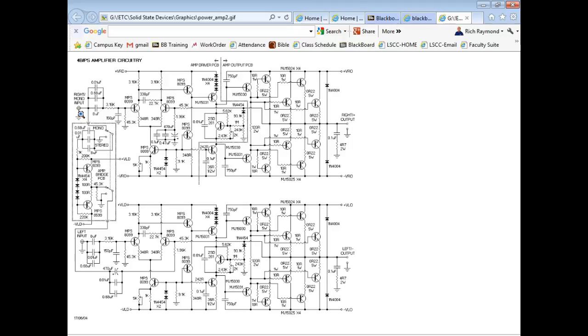So when we get power amps, we've got two ways. Most of the time, you can run them 2 different ways. You can run them as stereo, which means left, right, or you can run them what we call bridge. Y'all know what bridge is? Bridge is when we take your left and put it in parallel with your right, and we get a mono output. So it means I could have a 400 watt amplifier, and I split it 200 left, 200 right, you understand? Or I could use 2 400 watt amplifiers. I could run them bridged, and now I get 400 watts out of each side.